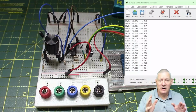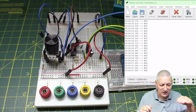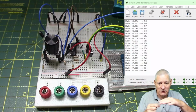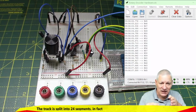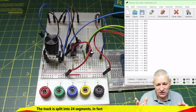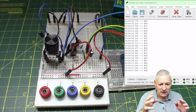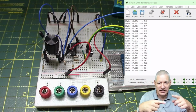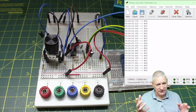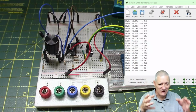They say if you turn it faster than that, we just cannot guarantee what's happening inside that pot anymore, as it's wiping the back surface, a bit like a potentiometer does. The wiper touches a track, doesn't it, on the back? Well, this does the same, except the track is chopped up into little bits, so it hits a bit of the track and then nothing, and then another bit of the track and then nothing, and so on. Rather than actual switches, like you might find, say, in a toggle switch. Again, when you spin it that fast, these wipers just behave erratically. You just cannot control them anymore. And this isn't switch bounce. Well, it might be related to switch bounce, but it's just the mechanical inertia and the fact that you're overdriving this now.